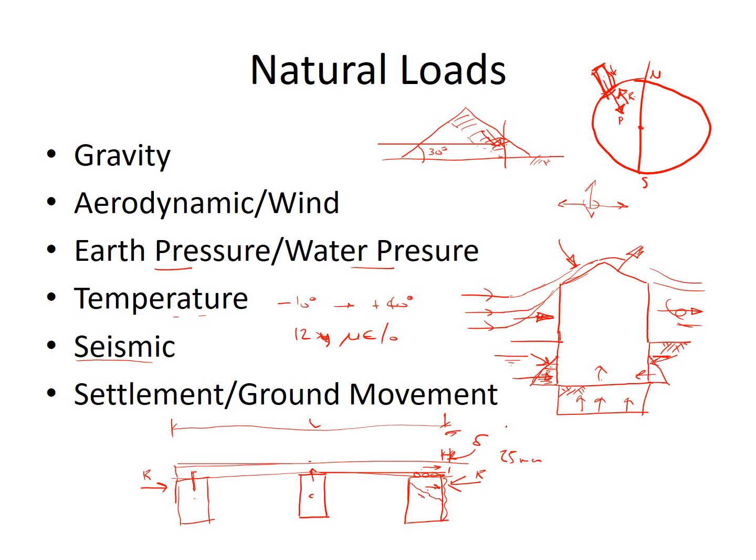And as such, the bending moment diagram of this continuous beam would give rise to a hogging moment at this location, a sagging moment here, coming to 0 at this pinned joint here. So you might get a bending moment in this structure with a hogging moment over this central support.